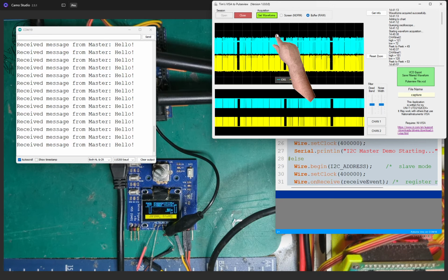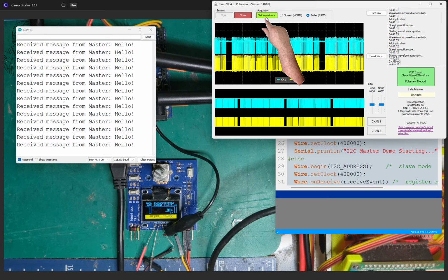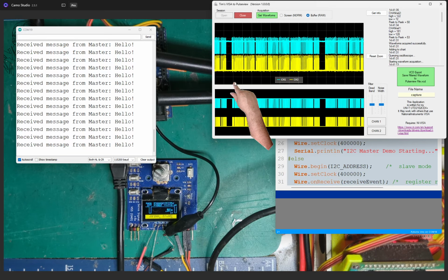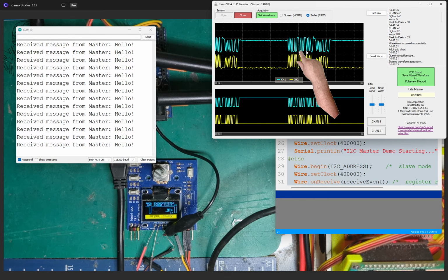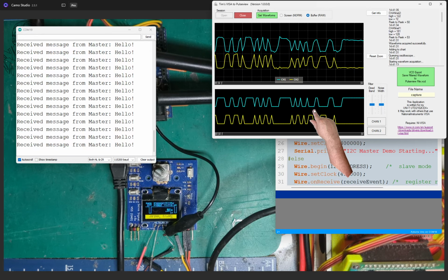Have I just redone that? No, I haven't. Yeah, that's better. Right, so if we get the waveform, I've got it down to sort of one thing, so now let's filter that. This is what I'm getting from my scope, and this is it filtered out. But it's still messy. This is what I'm trying to show with my scope, that it doesn't have enough memory to hold a decent resolution.